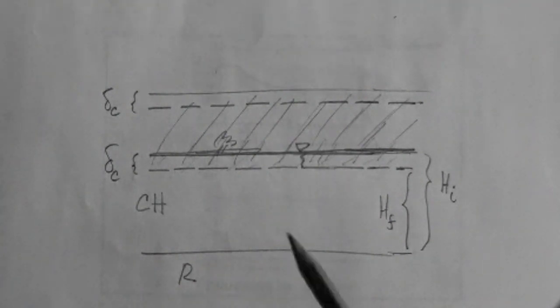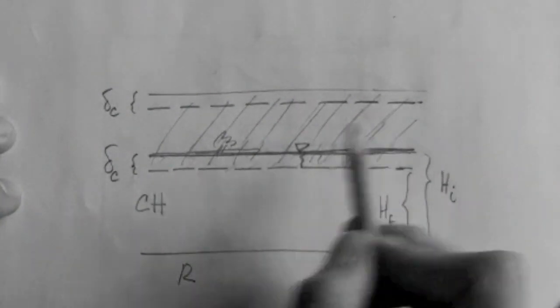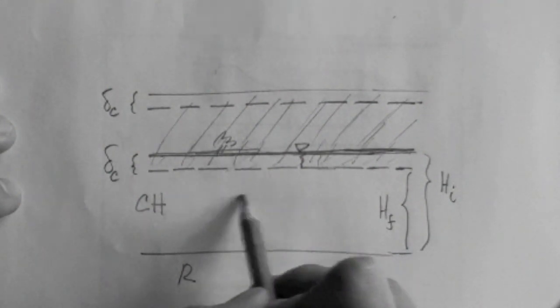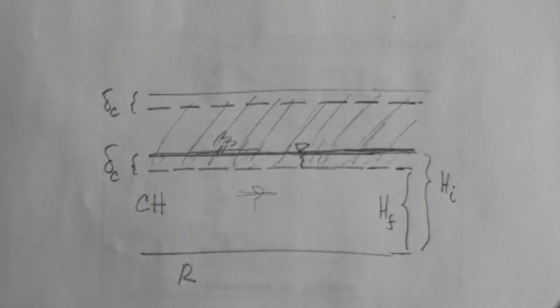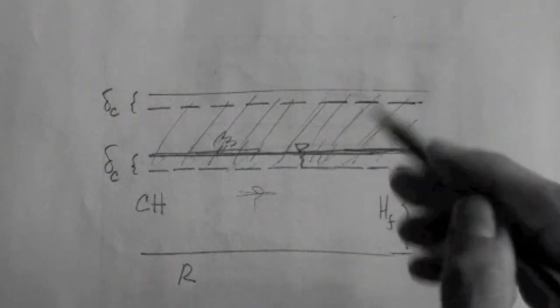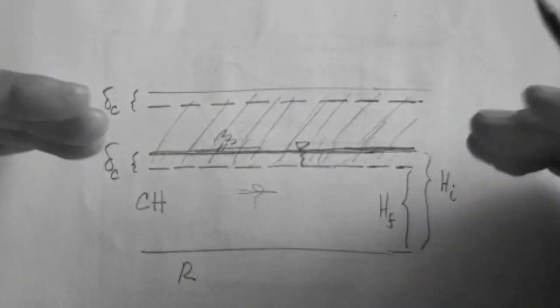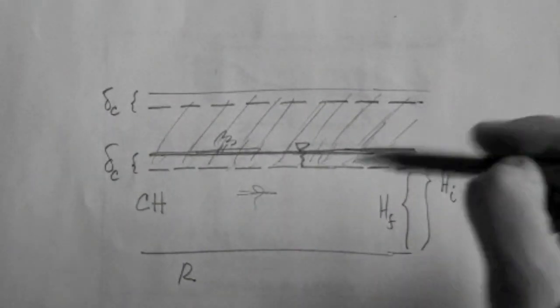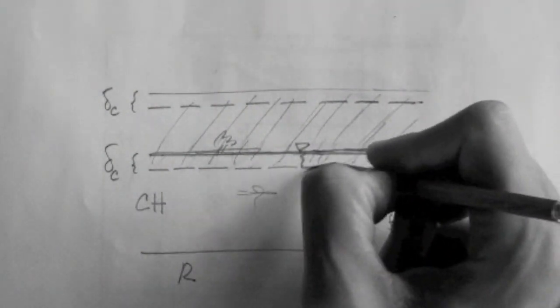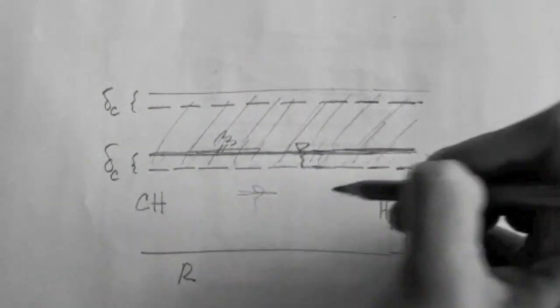Okay, but eventually it ends up at the same level, unless there is dewatering. If you come in here with a pump and reduce the water level to down here, then we have another problem, right? That's another type of problem. But the water essentially just remains there, and even though there's local flow from pore to pore, the whole water mass, as denoted by the water table, remains there. Okay, what changes is the location relative to the interfaces, because the soil deforms.